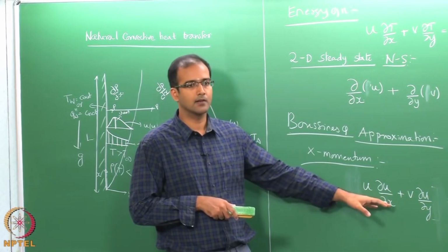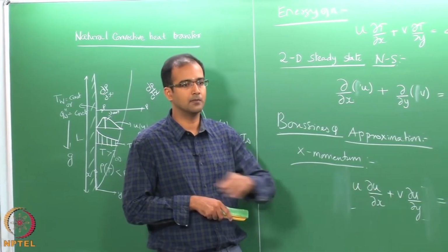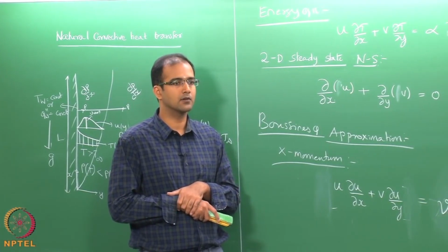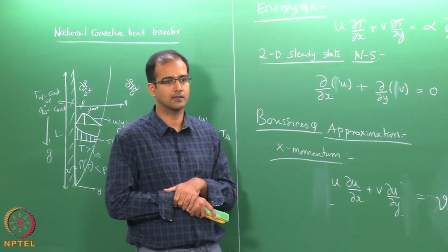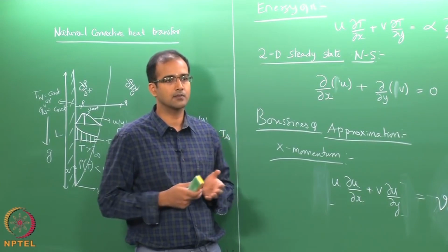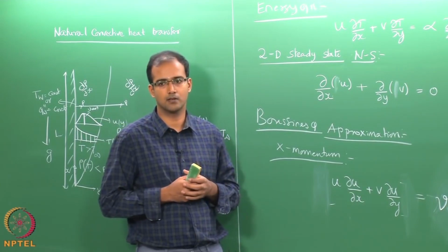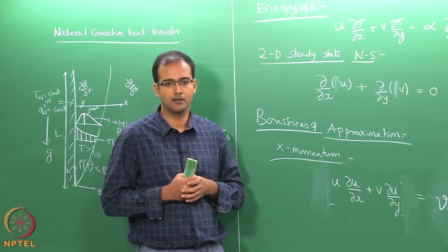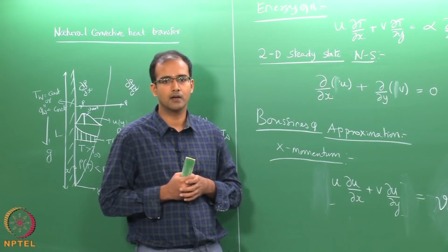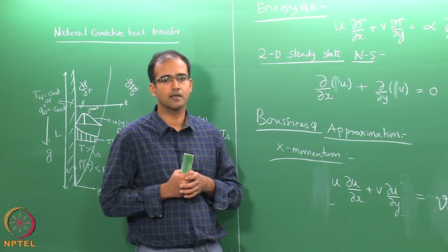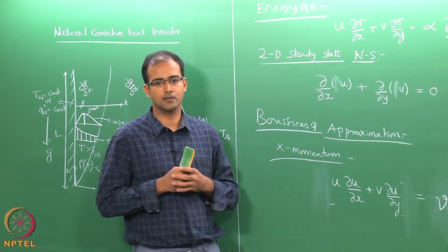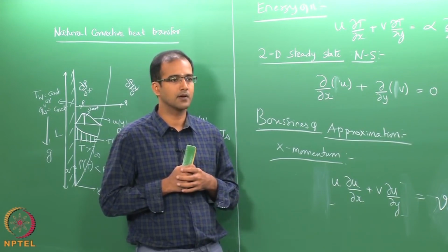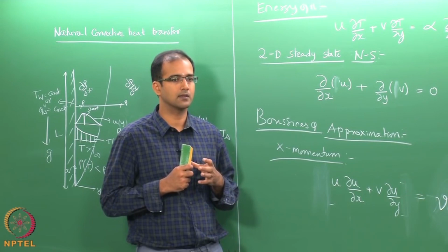But here the velocity profile itself is coming from the temperature. So, you cannot do it in a serial sequential fashion. All of these have to be simultaneously coupled and solved. Now, this is where the complication comes. That means you cannot find a simple sequential segregated solution unlike the case of external forced convection. So, you have to couple all these equations and solve them.